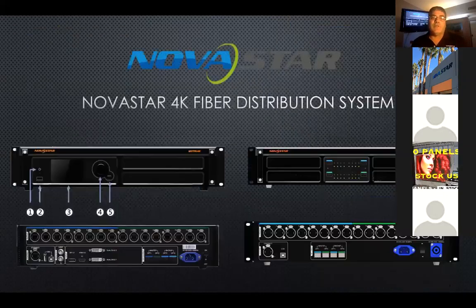Okay, so let's look at the NovaStar 4K fiber distribution system. It's made up of the MCTRL 4K and, for us, the CVT4S. So this gives you a strong backbone between the two of them. We'll go into detail on each of these products, but it is a partnership. You can't do it with one without the other. You can do a 4K wall with just the MCTRL, but you're going to be staying under that 300-foot limitation. If you need to get farther, then that's where the receiver, the CVT4S, comes into play.